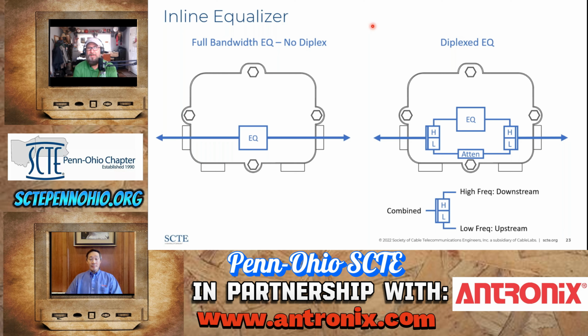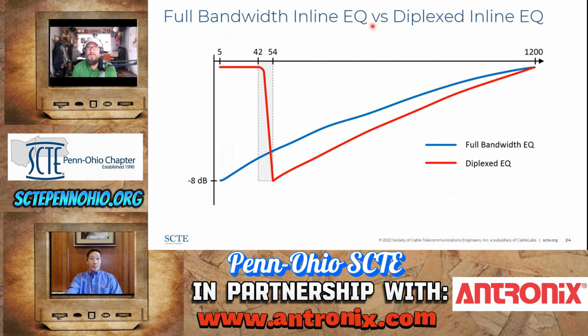And so we have seen this in systems that are going through mid-split or high-split upgrades, where these devices have to be identified and removed, because any device that's past it, meaning customer premise equipment, won't be able to leverage the additional upstream bandwidth of a mid-split or a high-split system because of the diplex filter in that device. So I think we'll talk about that in taps too, right?